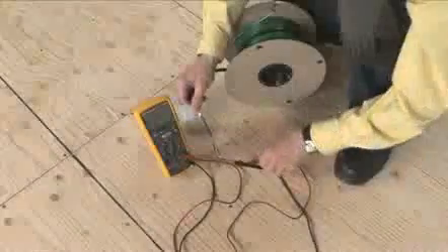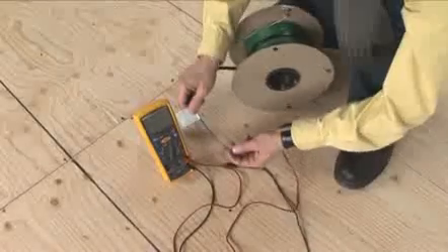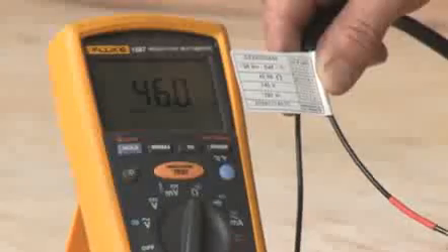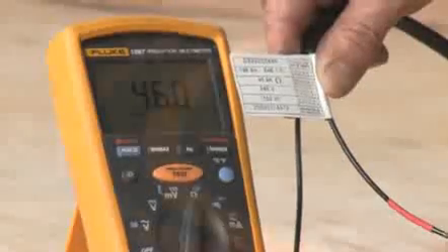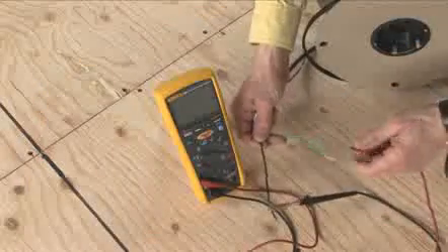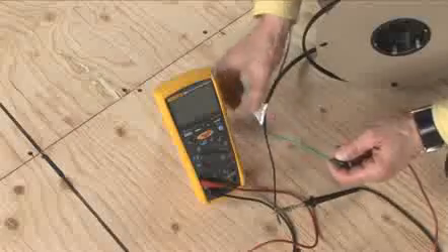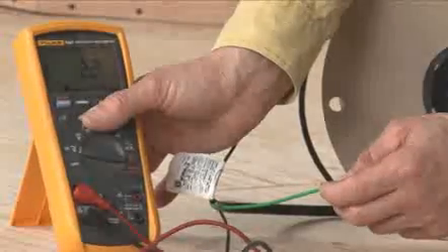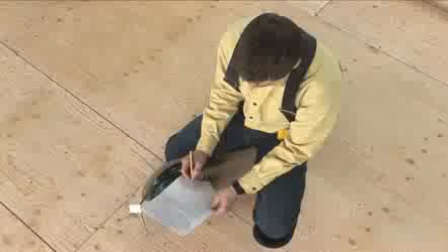Test the cable before breaking the seal. Check the resistance with a multimeter. The reading should be within 5% of the value on the cable label attached to the cable. Also, check the insulation using a megohmmeter. A reading of infinity confirms that the cable is good. Record the readings on the warranty card included in the package to validate the system warranty.